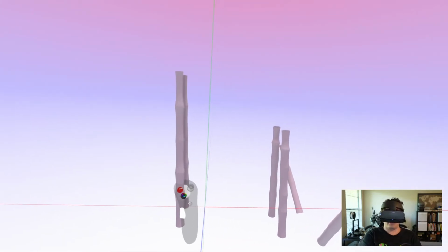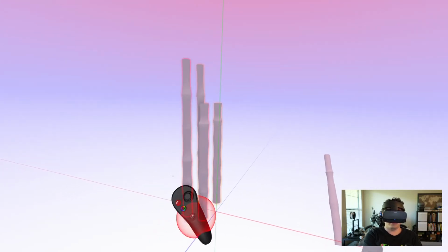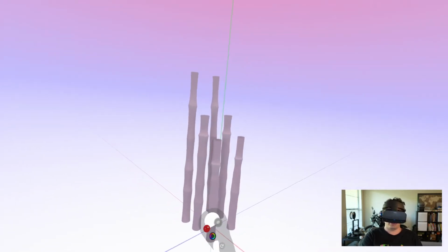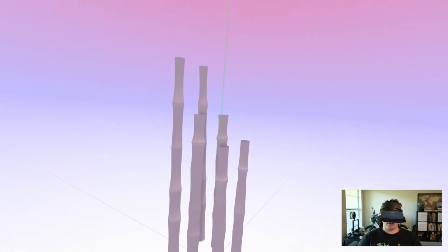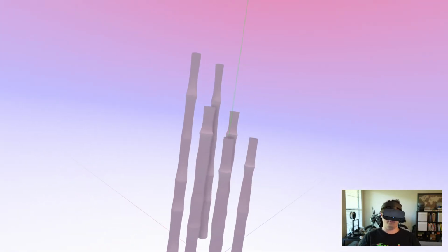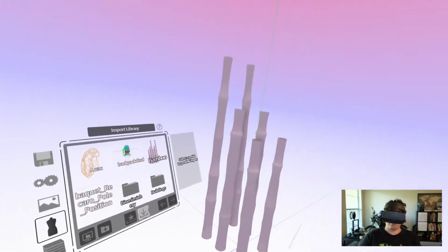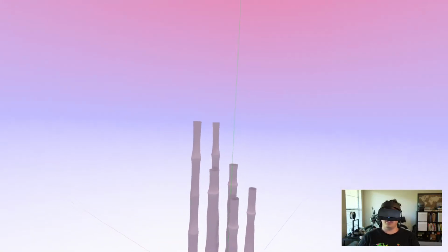But yeah, it's a really great way. If you find yourself using the same type of model a lot, and you say, hey, I just want to make this once and I'll use it over and over again, just start a file, create it in Gravity Sketch, save it as a prefab. Like we said, we just grab the object, save it, drop it in the prefab folder, name it. Then you've got it in your folders, and you can bring it into any other sketch.